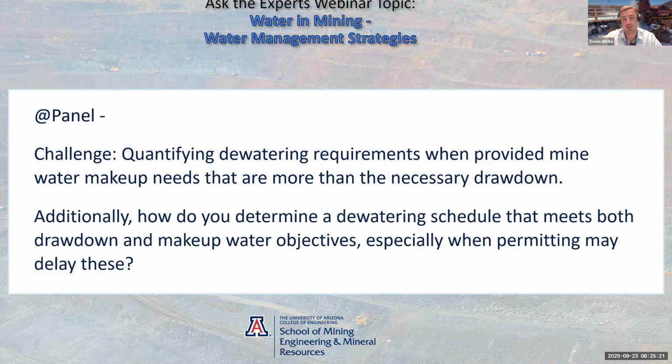To give an example, in an underground environment, when you're designing a pumping system, you typically design it for 200% of the nominal pumping rate, and that's to bring in that flexibility and redundancy, so that when you have breakdowns, which will happen, you can then recover, and the same goes for bringing water in.